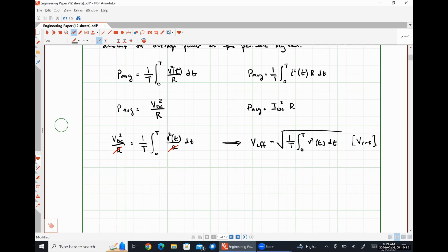So let's talk about where this RMS thing comes from. RMS stands for root mean squared. It is literally just telling us the mathematical operations we are doing to get the effective value. We are taking the square root, that's the R, of the arithmetic mean, that's just a fancy word for average value, of the square of the waveform in question.